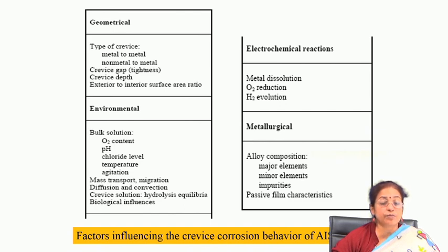Crevice depth is also very important. As you go on changing the depth, you will find that the attack rate will usually be more, because on the surface the attack rate is much lower, since it is exposed to the environment. So there is the possibility of oxide layer formation. As you proceed towards the depth, there will be less oxygen supply or less air supply, as a result of which there will be more tendency for crevice corrosion.